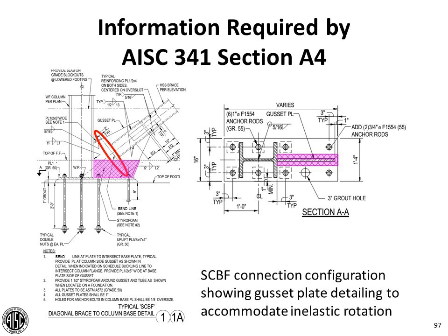Larry mentioned the requirement that the gusset plate details be drawn in such a way that they communicate where and how inelastic deformation needs to be accommodated within the connection itself. And so this is an example of a special concentrically braced frame where the engineer has determined that the design intent is to allow the braces to buckle out of plane. And in doing that, it will create, and there are a variety of different terms that are used.